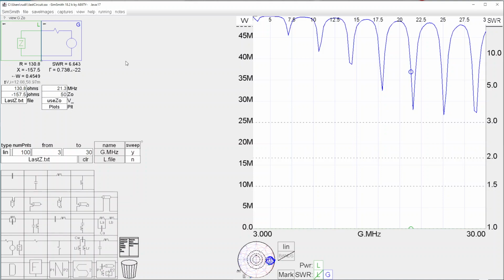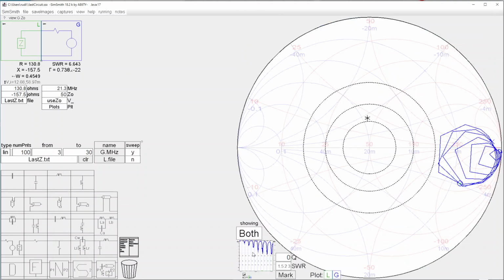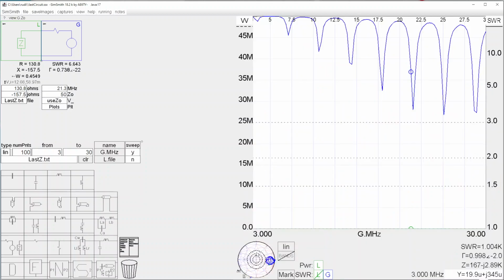And this is the same curve you see in SimSmith. So here's the SimSmith analysis. And again, you can see that it's all bunched up and curled, wrapped around the 3 o'clock end of high impedance. So we need to go from here, and let's pick what band we want to tune up on. Let's tune up on 10 meters. All right, and so let's analyze this at 28.4, and that'll be our analysis point.